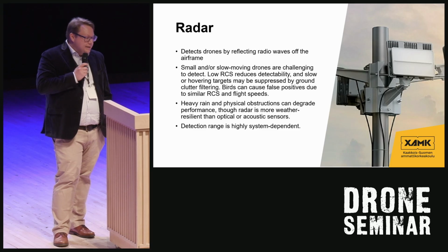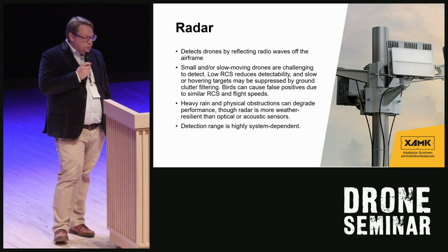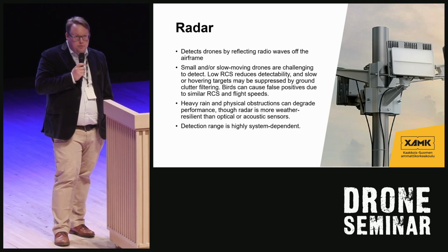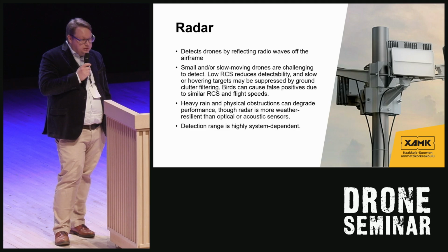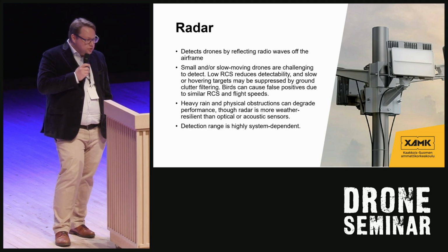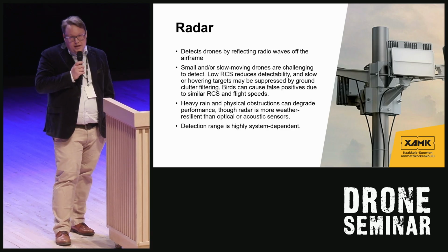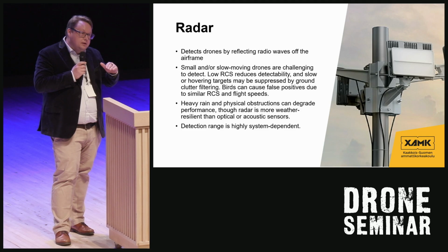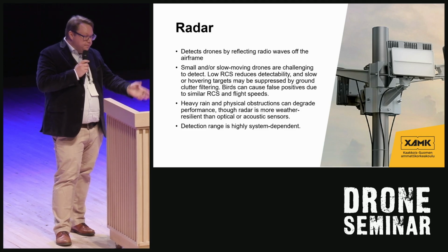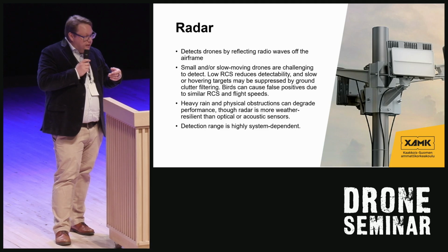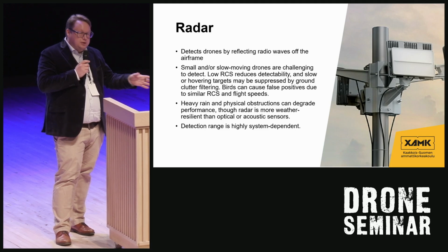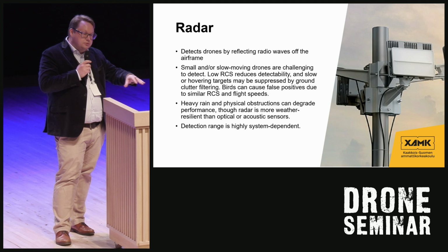So the smaller the drone, the more difficult it is to detect with radar. Also, if the drone is flying at a very low level, these echoes are mixed with ground clutter, because you have objects on the ground and those will also give some echoes back.